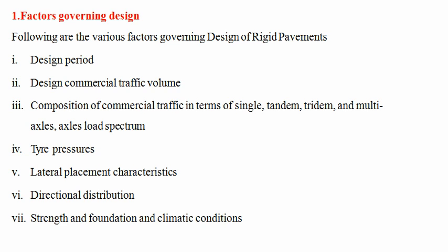and lastly the strength of the foundation and the climatic conditions existing at the site, because the characteristics of the type of strata available for the foundation on which the subgrade has to rest will influence the selection of the entire material used for construction. At the same time, it will also influence the total depth of the pavement. The climatic conditions will again affect the design, such as the provision of camber, drainage and sub-drainage facilities to be provided for the pavement.